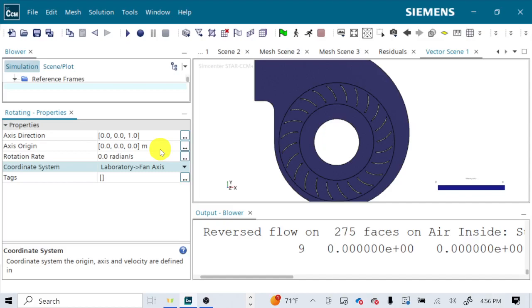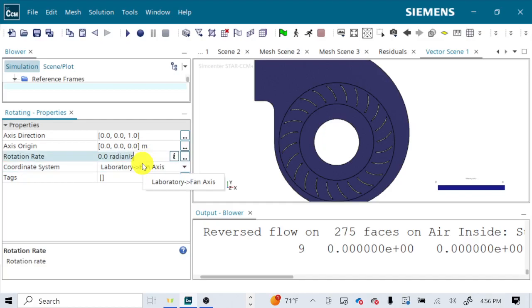And we get to tell it how fast it's rotating. This is where you've got to be really careful to make sure it takes your units properly, because if you tell it 500 RPM, that's very different than 500 radians per second. It's almost an order of magnitude difference. So let's give it 500 RPM and see what it says. It definitely did say 500 RPM. You can't read it, but it says 500 RPM, not radians per second, so that's good.